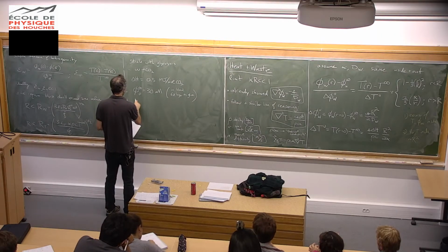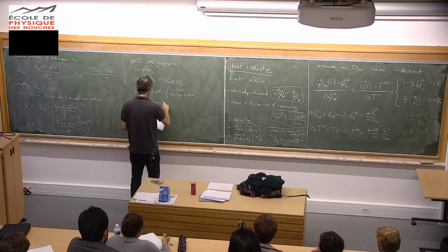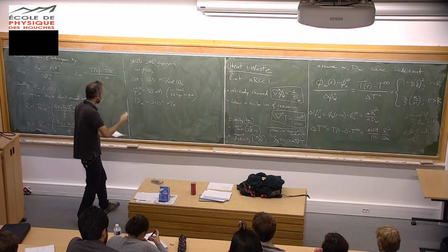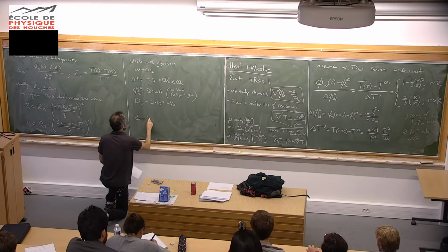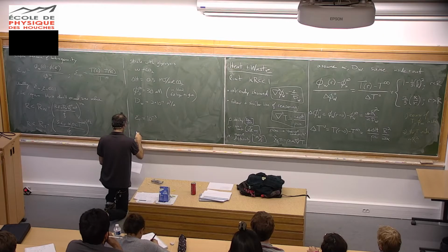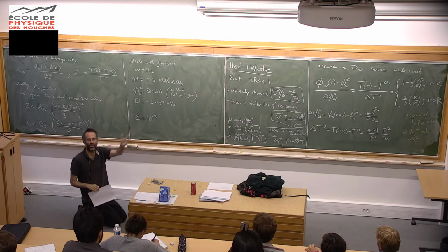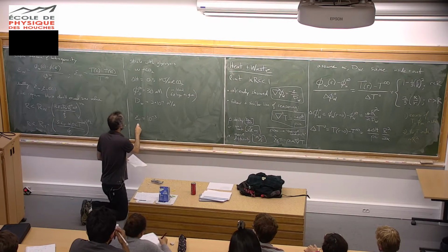And then the diffusion coefficient of carbon dioxide in water, you can look it up, and it's 2 times 10 to the minus 9 meters squared per second. And if I somewhat arbitrarily set a cutoff of homogeneity of 10 to the minus 3, so 10 to the minus 3 for temperature would correspond to like 0.3 Kelvin, I don't know if that's a small or a big temperature difference.